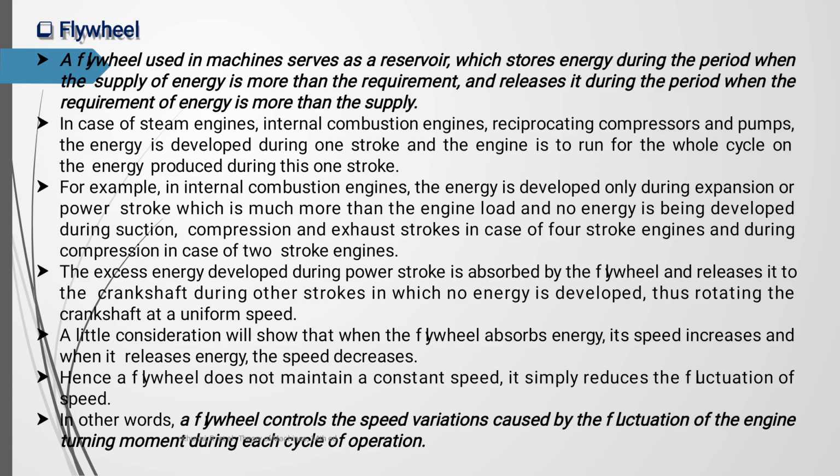I've already told you, in the remaining three strokes there is no energy developed during the suction, compression, and exhaust strokes. In the case of the four-stroke engine, we already saw that the excess energy developed during the power stroke is absorbed by the flywheel and released to the crankshaft during the other strokes in which no energy is developed, thus rotating the crankshaft at a uniform speed. I already explained these points at the time of explaining the working of four-stroke engines.